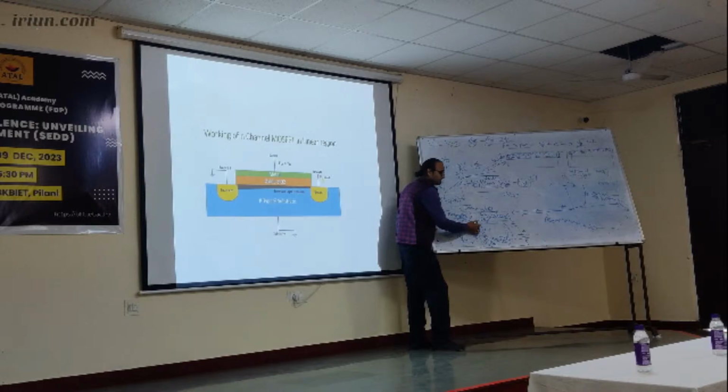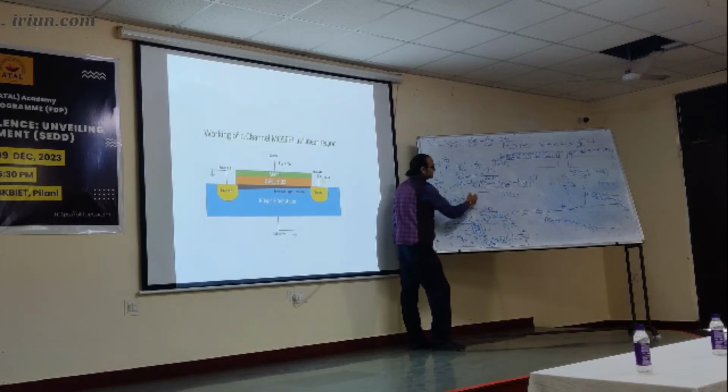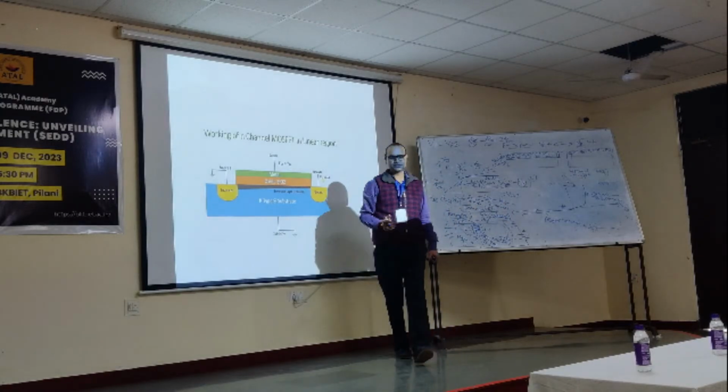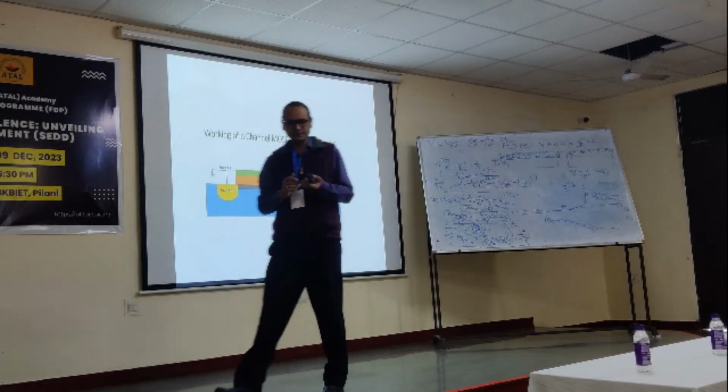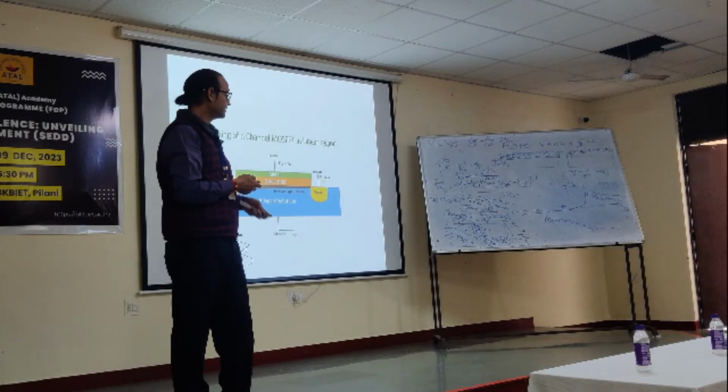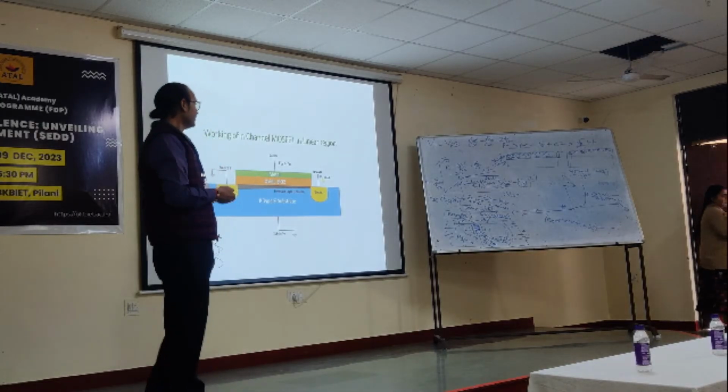This will also behave like a diode, but it will not meet that structure, that end-to-end connection. It will not meet the requirements of a transistor. What do we want in a transistor? We want IC to be large, IE to be also large, base area should be very thin, and IB to be very small, ideally zero. We are not able to achieve that in case of end-to-end connected diodes. They are not fabricated as well.